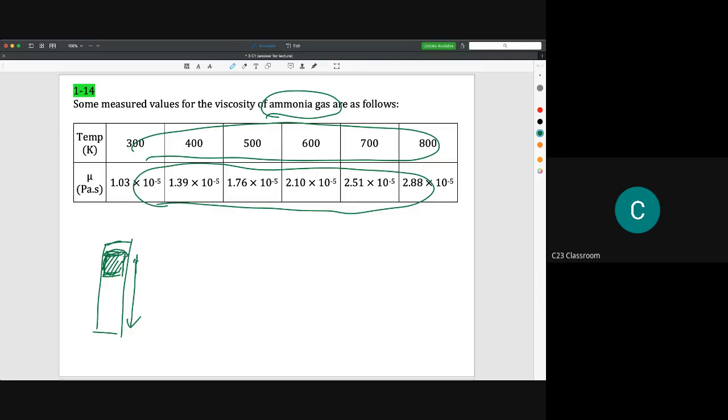Why? Because the gas actually resists the object here, so you need to do something with the weight here, but at the same time the gas will flow into this gap slowly, and this will make the object fall down at a certain speed and at a certain force. By using this idea, we could estimate the viscosity of certain gases.